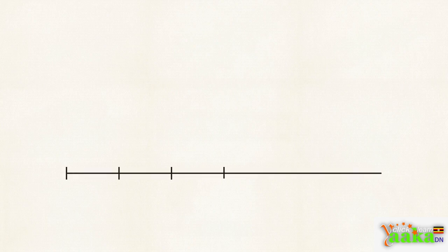Next, we plan the construction. To measure up to 6 meters, we divide this line into 6 equal blocks. Each segment represents exactly 1 meter. The 0 mark drops in at the first internal tick mark. From there, label the whole meters, 1 through 5, moving right. That leaves a single empty block to the left of 0. We divide it into 10 equal parts. Each small division represents 1 decimeter, or 0.1 meters.